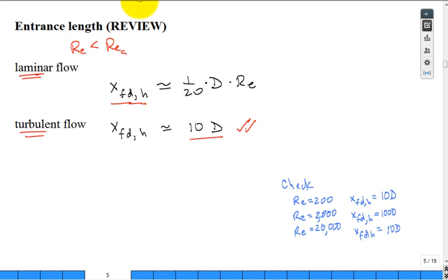And a lot of times I've worked with different people, and they'll put a flow meter in, and they're very careful to put a flow meter such that you don't have some obstruction or some change in the piping system at least 10 diameters before you hit that flow meter. Because the flow meter counts on a certain profile, even if it's turbulent.